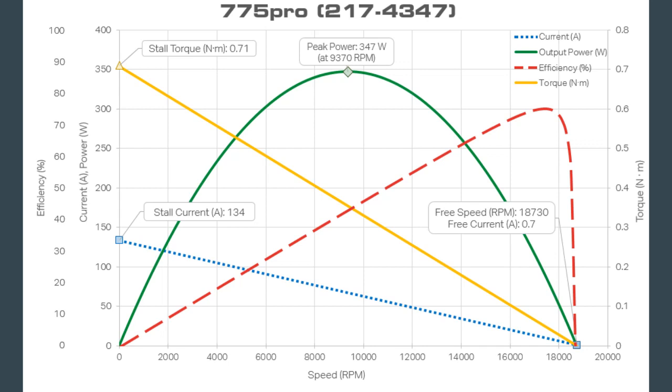I'm still learning this. So, because engineers are conservative, notice your efficiency is better when you're at lower percent stall torque, but it's kind of more complicated. I guess I don't completely understand it, but the general idea is you want to design for like 20% stall torque over here, and then if let's say your arm runs into something, now you have more power that you can give. So you move up. When the load increases, you're going to move up to a larger stall torque.